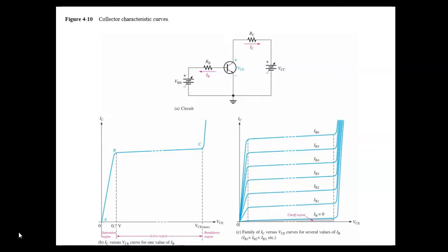Basically, what we do is we just start at the, I don't know if we should do the maximum or set it off for maybe 6 volts. But what you can actually see happen is that for a certain voltage collector to emitter, for a certain base current, this line right here is not exactly flat. It just goes up a little bit. But then when you exceed that, can you see what happens on the right-hand side over here? That sucker just took off. So this happened when we got up to around 8 volts. That's when it actually took off.